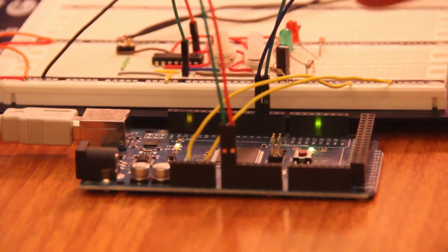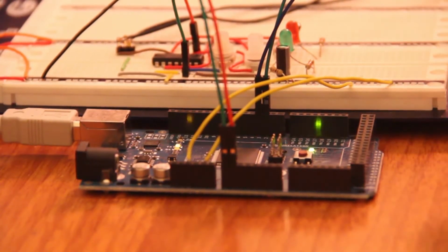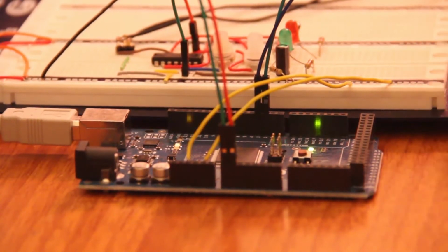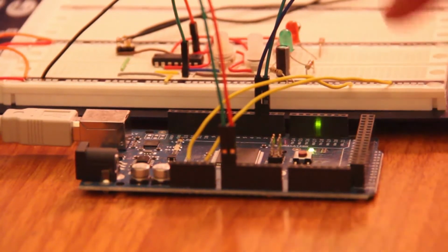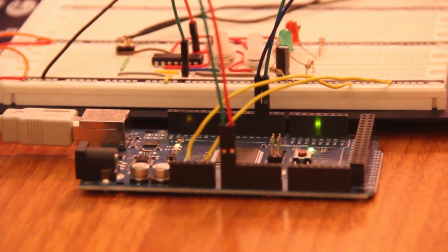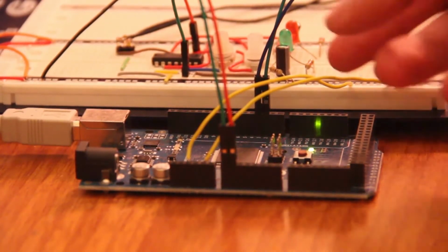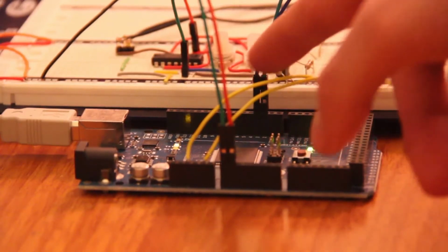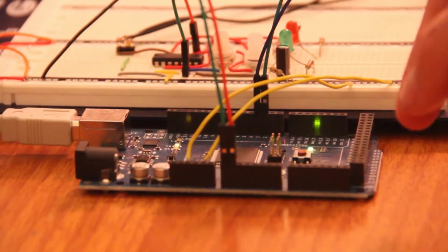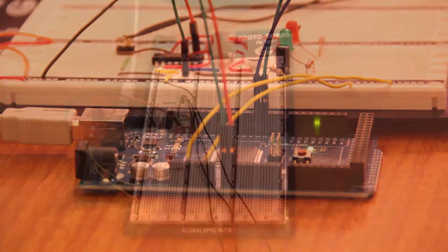Let's not forget that this system has to have 5-volt power, although it's not necessary to power it with the large, bulky computer power supply that we're using for the LEDs though. So we're hooking it up to the 5-volt and ground from the Arduino so that the op amp has the power it needs to do all the amplification. And then the last thing here is don't forget to hook up the signal and clock lines from our LED strip that we showed earlier.